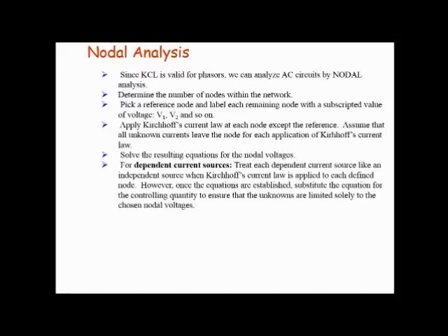Now we need to apply Kirchhoff's current law at each node except the reference node. Assume that all the unknown currents leave the node for each application of Kirchhoff's current law. Then we need to solve the resulting equations for the nodal voltages.